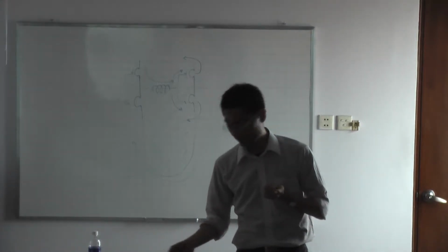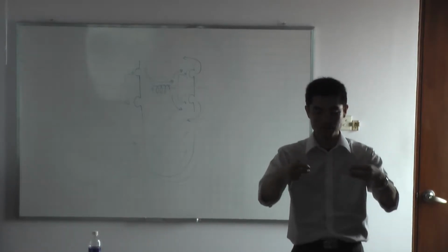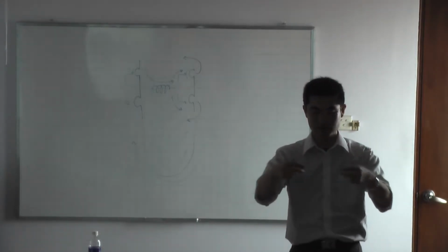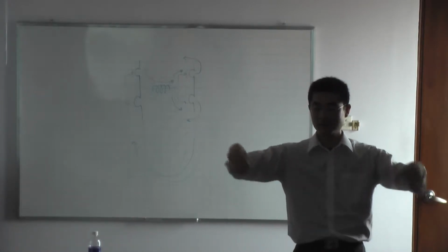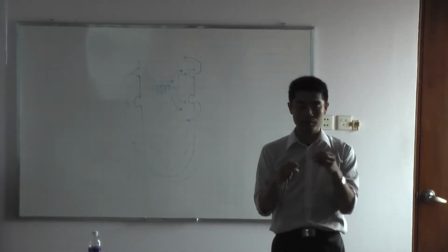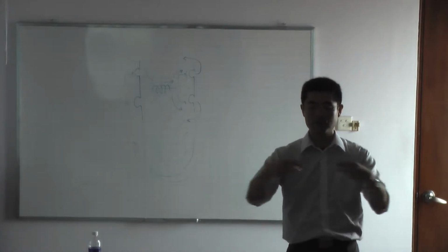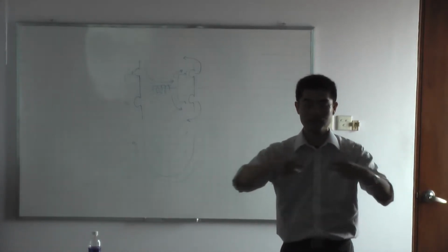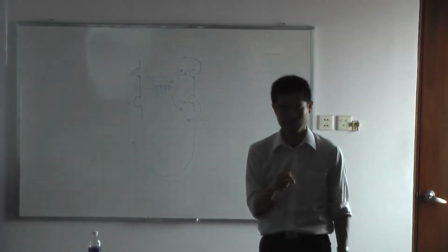So in the dividers, we have 50 ohm impedances in parallel, then connected to the 50 ohm. So from the input terminal, it will have two 100 ohm terminations, and that is equivalent to a 50 ohm termination.